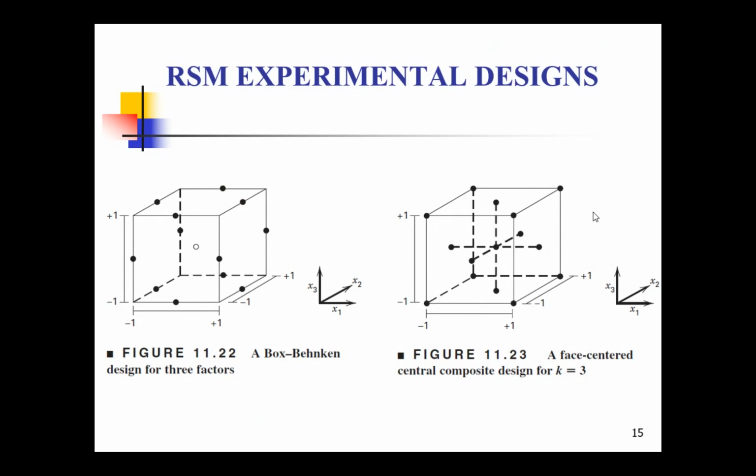But in the case of Taguchi, if I am going to consider 3 levels or 4 levels or 5 levels, for each level I have to provide the level values. But in the case of RSM, we have to provide only the lower and the upper limit values for the input parameters. The intermediate values will be taken care of by the system itself.